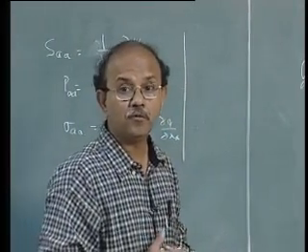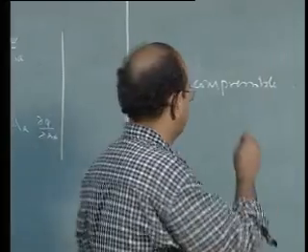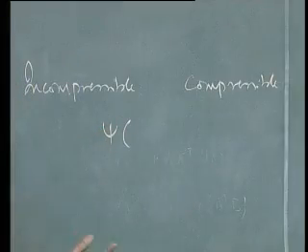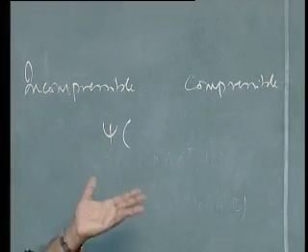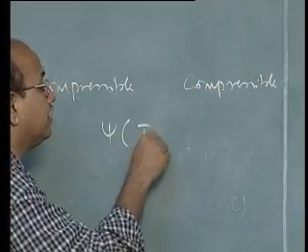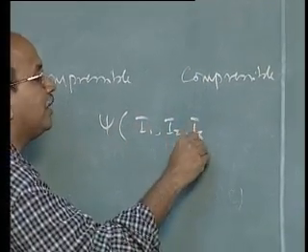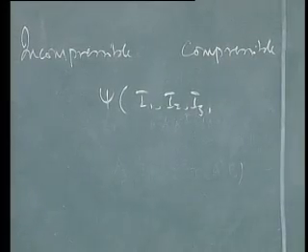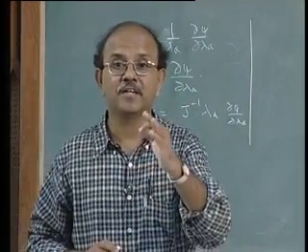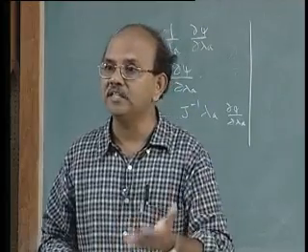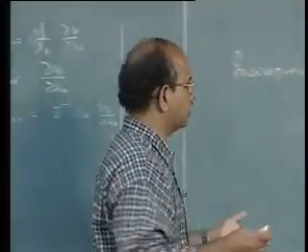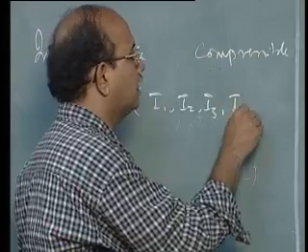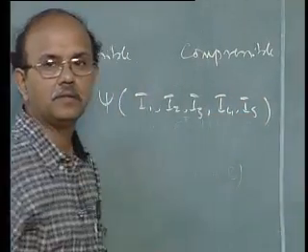In other words, we can't represent this psi which I had done before in terms of I1, I2 and I3. In fact, interestingly, for an anisotropic material, what we need is more number of this kind of invariants. And these invariants are sometimes called, say, I4, I5 and so on.